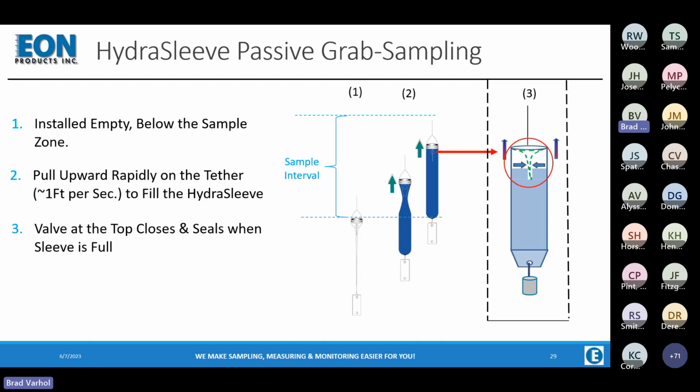So as the sampler is pulled out of the well, it is not influenced and does not capture any of the overlying water layers. The water itself does not move, so that's an important point. Only the sampler moves. And by the way, I think of this like when I get up in the morning, I put my socks on, and when I have a sock, what is it? It's a tube that's sealed on the bottom.